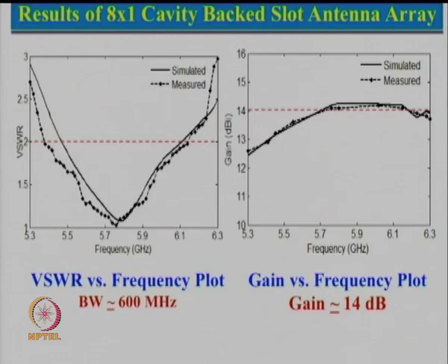So, now we have discussed different types of slot antenna. We actually saw parametric studies. It is very important whenever you are designing an antenna to do a parametric study and see the effects of various parameters, because that helps you design an optimum antenna, where you can do proper impedance matching, and proper matching of the gain or the radiation pattern requirements.